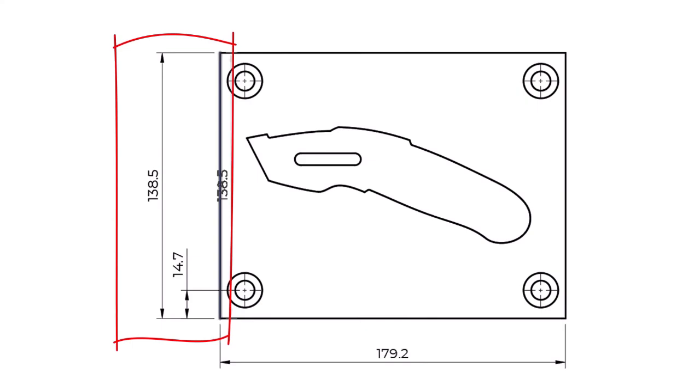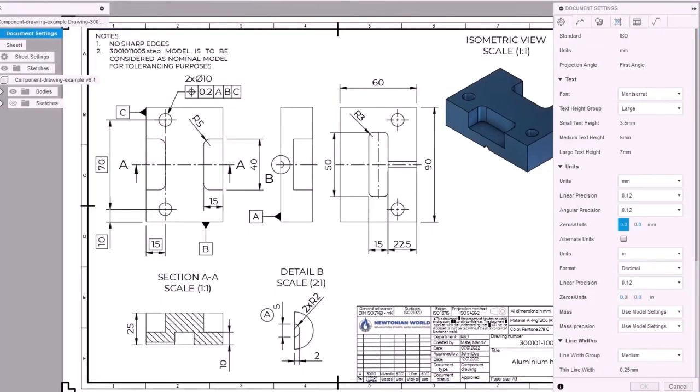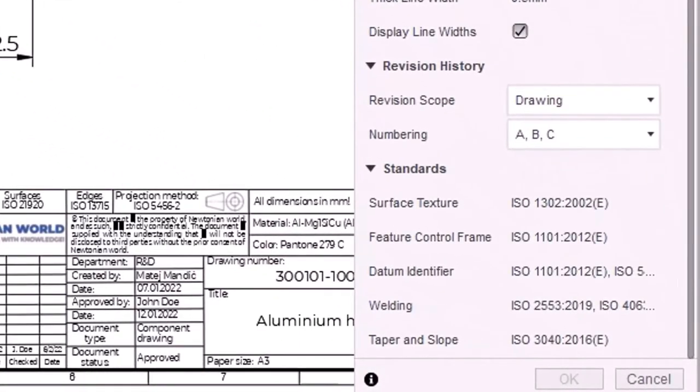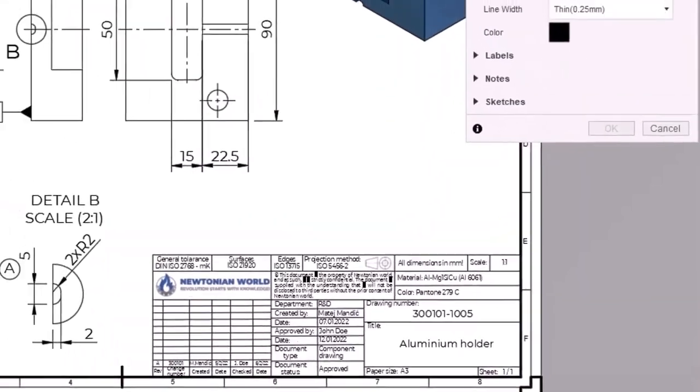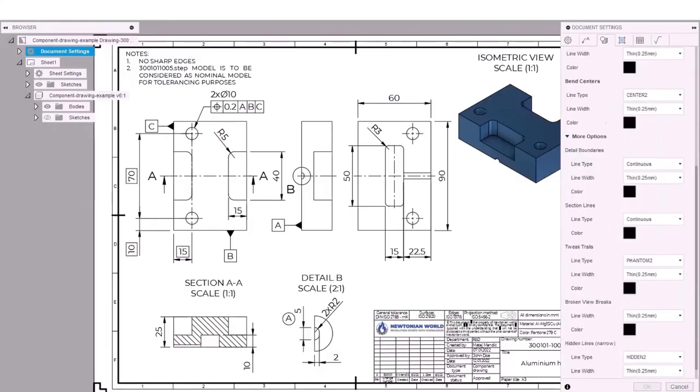The rules for the dimensioning are defined by ISO 129-1:2018. In the real world, most engineering companies use CAD software for designing products and for creating engineering drawings. Most CAD software already contains different standard rules for creating drawings. With that being said, we will not dissect every rule to its core. At this point, I think that it is good enough for you to learn the basic terminology of dimensioning and then move to perfect your craft of dimensioning drawings unambiguously. Extension line, dimension line, nominal value, and terminators.